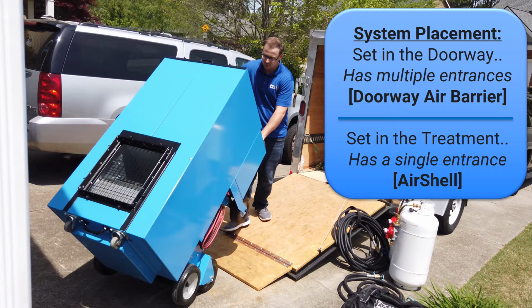If there is only a single entry into this structure, we're going to have to use something called the air shell. This is something that wraps around the controls, allows you to place the machine in the heat treatment and run a duct to the window. Through that duct will flow the actual gas line, the fresh air for combustion, fresh air to flow across the controls and the motors, as well as pressurization near the end of the treatment.